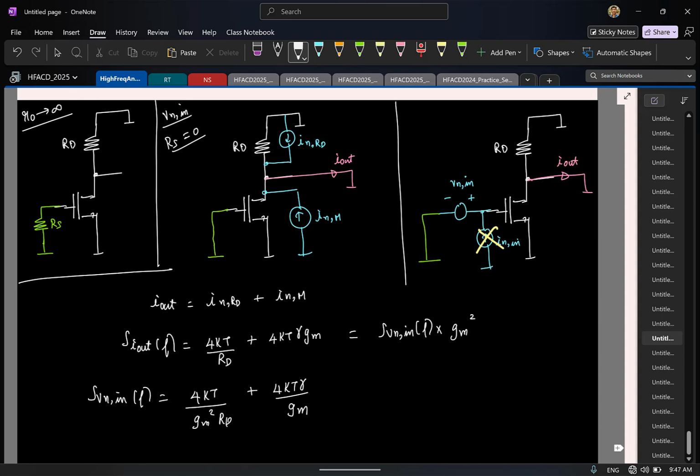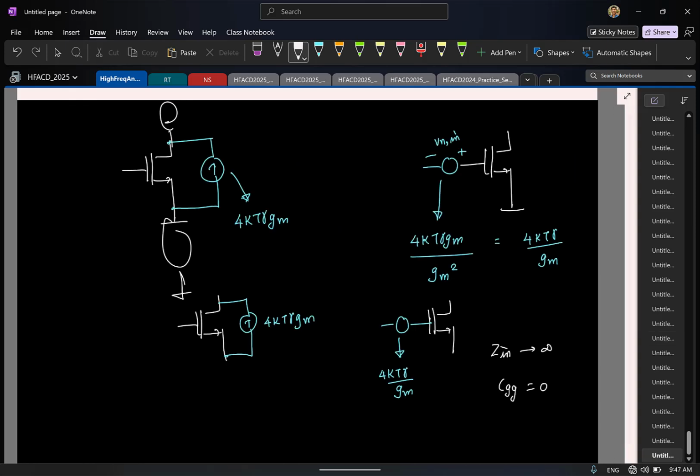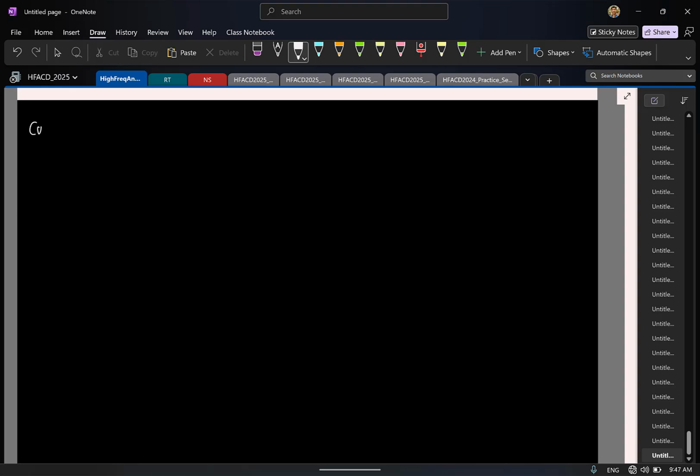So just look at one last case, and that will be your dear friend, the Cascode. I'm sure you use Cascode back and forth to increase the gain in your design project. So let's see what happens. I'll just consider an NMOS Cascode like this, incrementally short, and here is where I apply the input, here is where I take the output. First let's even ignore r0.